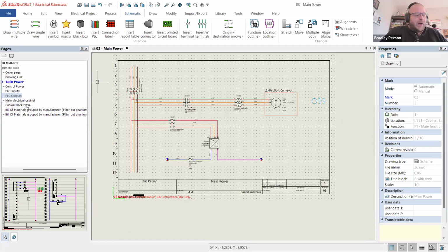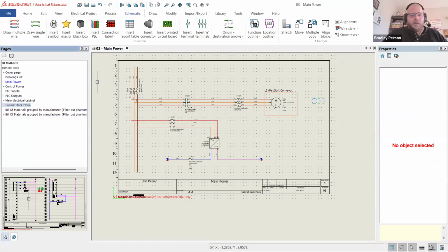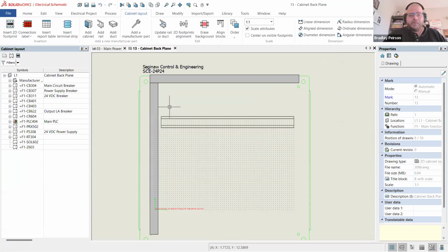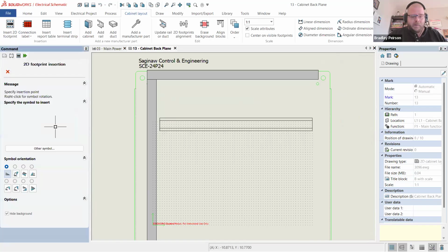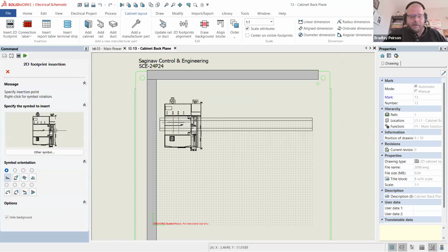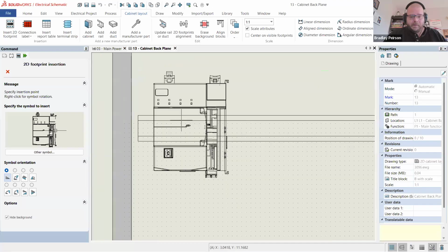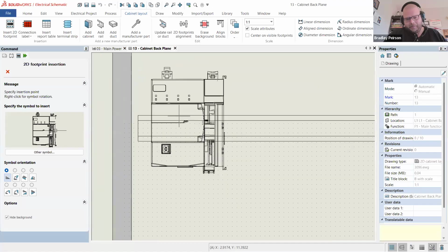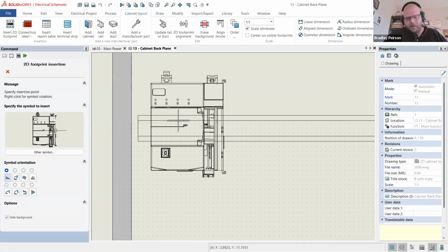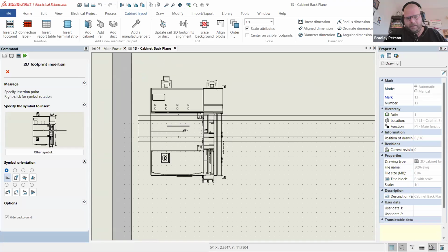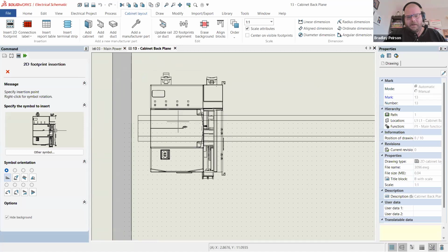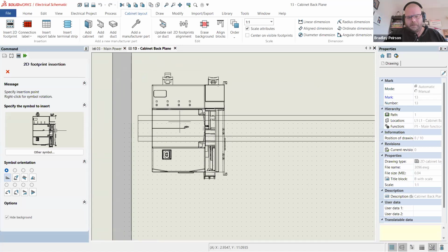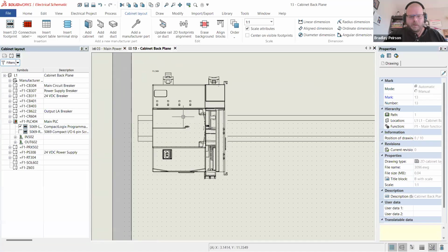So from there, getting the rest of the 2D schematics in is fairly simple. I already demonstrated with the PLC, right? I just check this 2D symbol and drop it in here. Try to center. I can't honestly, off the top of my head, remember where the actual DIN rail mount is. I think it's centered on this family PLC. So it's just a guess. I mean, as long as it's oriented somewhat close to that DIN rail, it doesn't really matter.